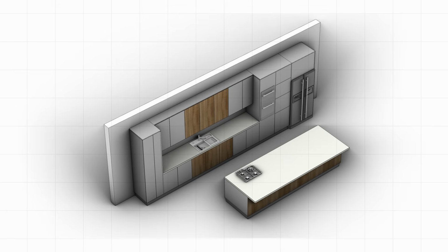The width of the island is also very important. For enough workspace and smooth circulation, a width of 120 to 150 centimeters is generally recommended. In this project, we've set it to 150 centimeters, providing both easy movement and sufficient countertop space.